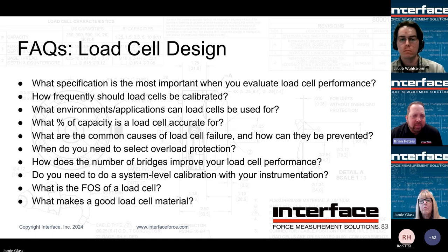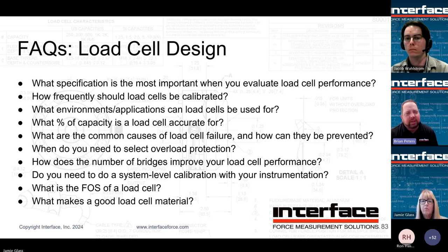So again, we have some options there, but typically you can often handle this too with just how you have it calibrated, right? You can always upsize the load cell capacity, ask for specific cal points, and now in theory, you still have confidence in the test range, but still have a much stronger load cell that can tolerate more mechanical load.